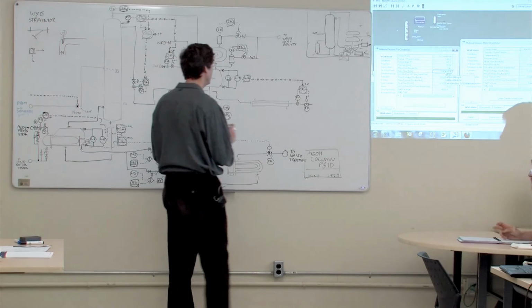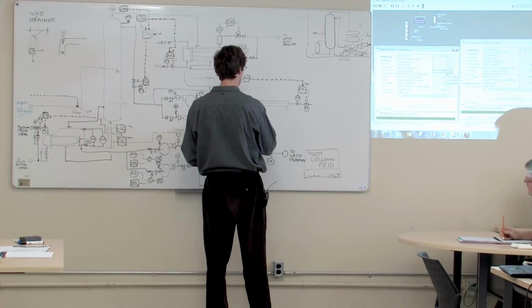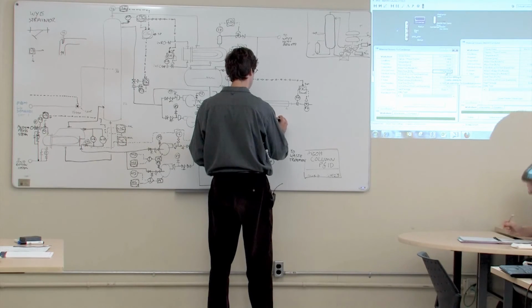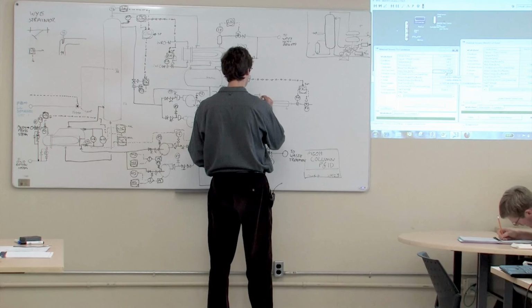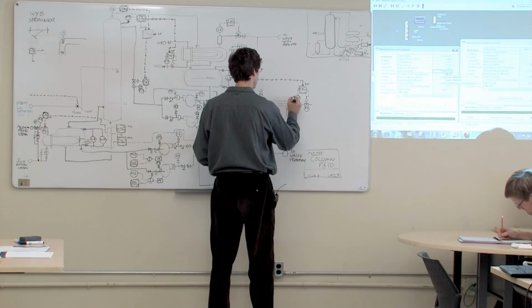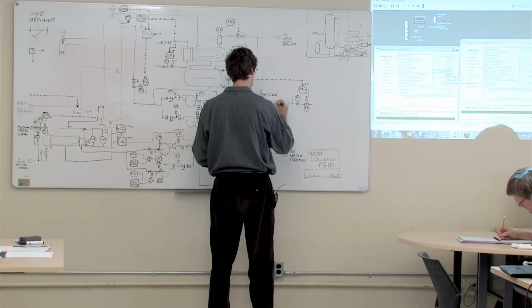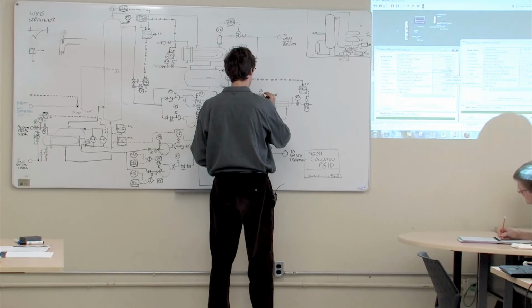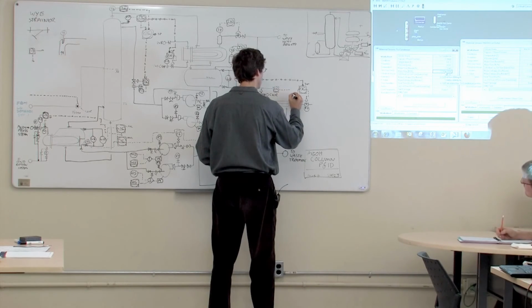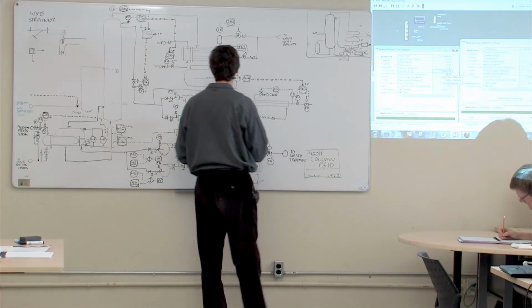Oh, we're missing some cooling water here, sugar. Okay, so we want some cooling water supply here. I'm going to put my cooling water line here. I need a TE. Let's fail that open maybe. And TIC in the DCS. TE here, like that.